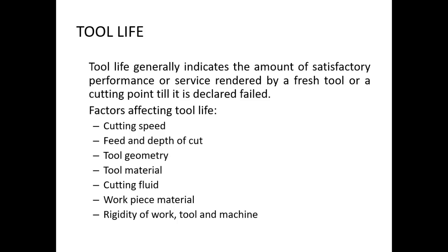It means I can do the machining operation for 2 hours or 3 hours or 4 hours, and so on. It means how effectively the tool has performed. It is nothing but tool life. So what are the different factors that affect tool life? Cutting speed: if I increase the speed, obviously the tool life will be less.